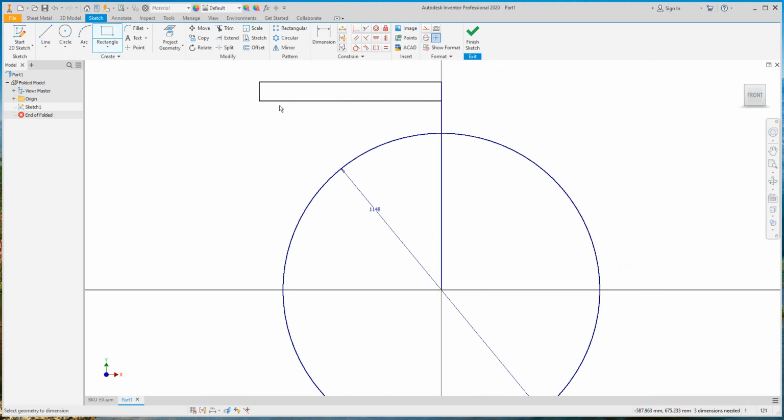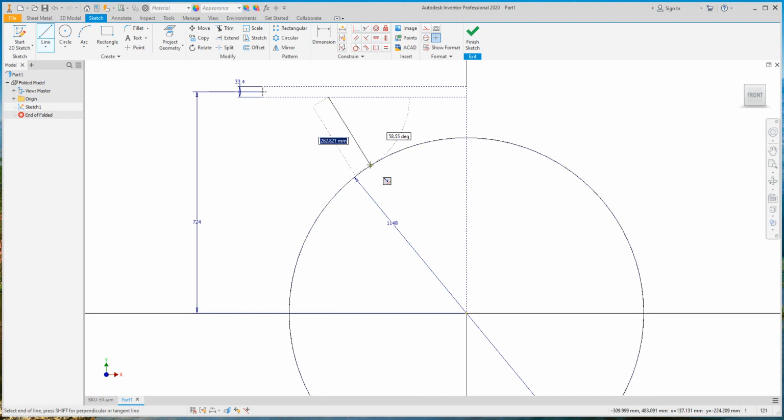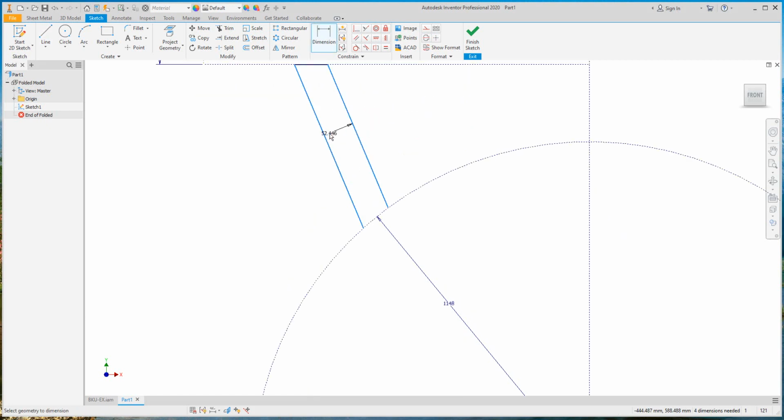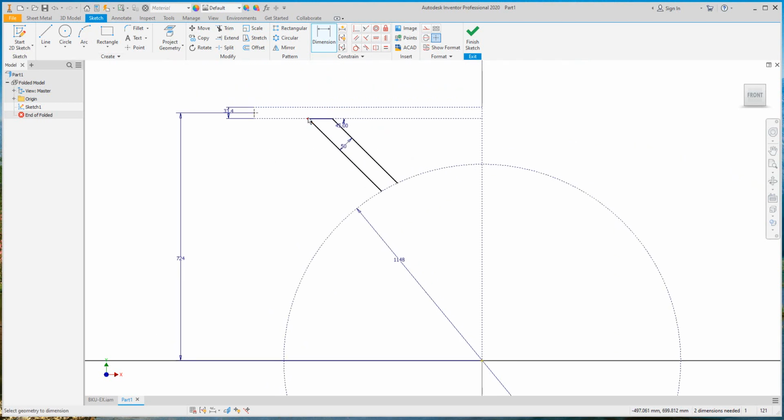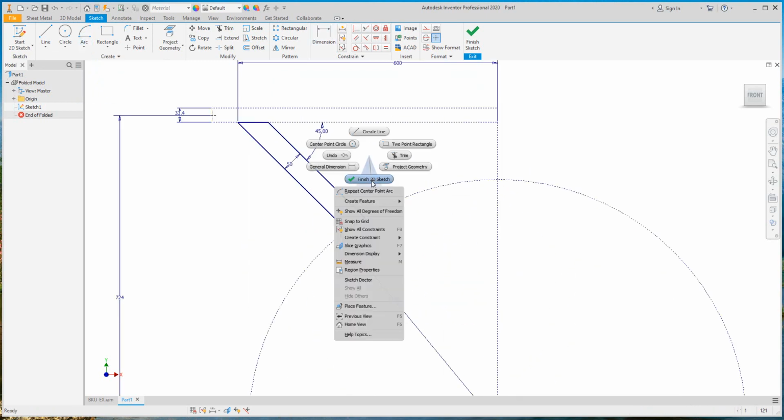After creating a new part, we will create a new sketch, define some dimensions regarding the pipe location, and offset from visual center line, define the tube diameter. After that, we will start creating these dimensions of the support, define the width, the tilted angle, define the offset from the visual center line, and complete the sketch. Now the sketch is closed.